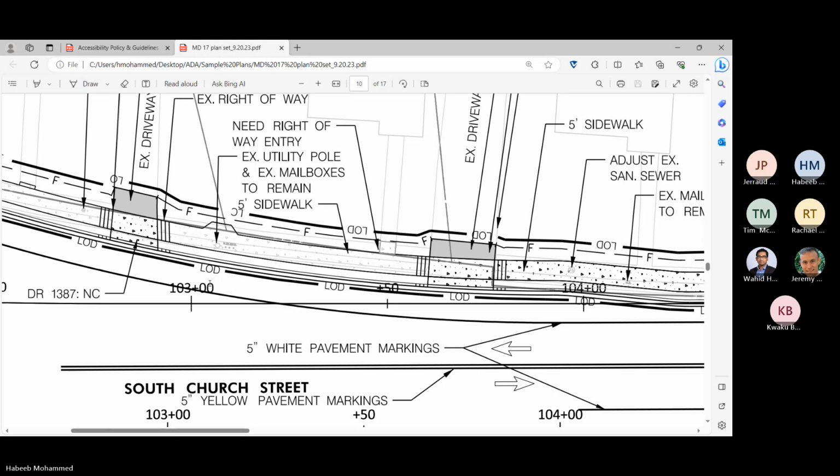For which one? The back slope behind the driveway. What is the max you can go? I believe it's 8%, but I'll have to double check on that. Yeah, I mean, there could be places where the driveway tie-ins could go way far, but we use like 10% slope and try to tie in as little as possible.